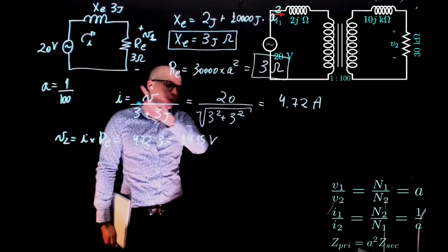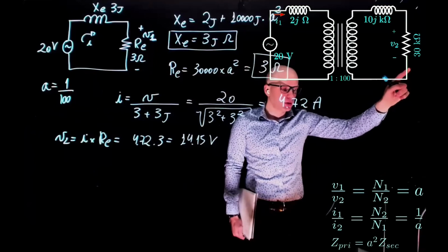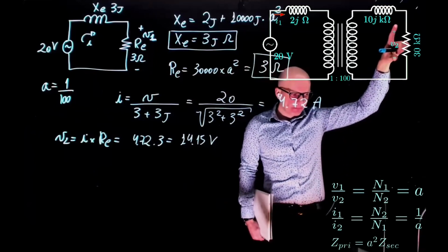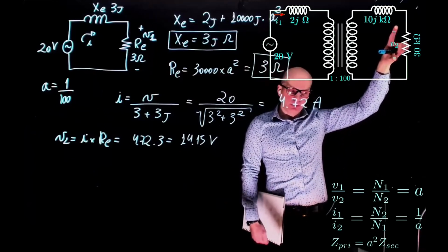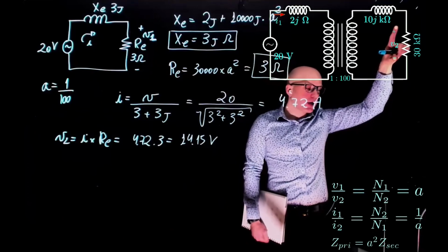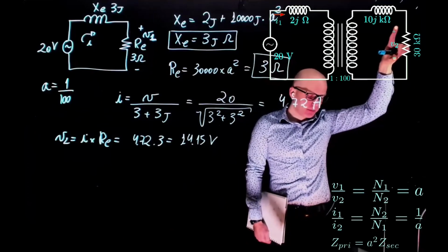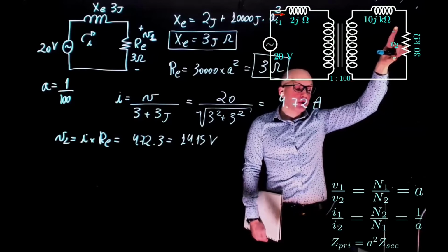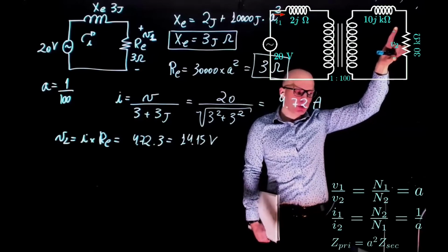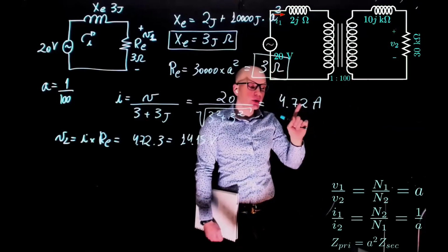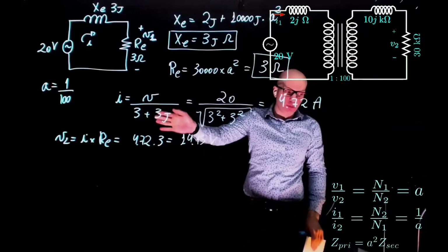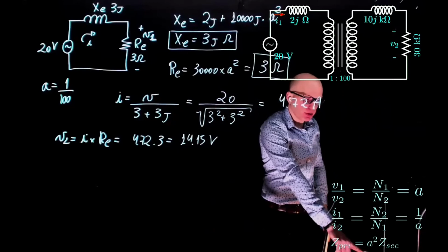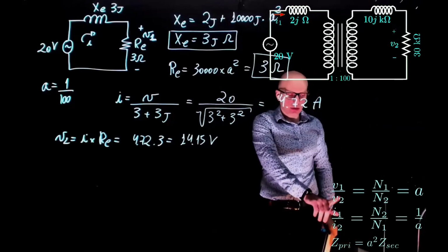How do we move this voltage now to the actual load here? A squared or A? Just A. Very important. Again, a common mistake that I see in midterms. Now we are dealing with voltage. All the transfer that we did before was for impedance. Impedance is squared, right?